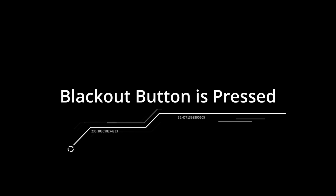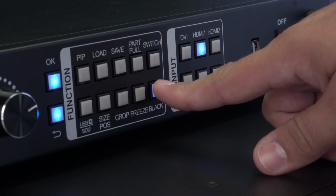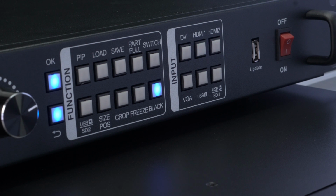The blackout button is pressed. Verify that the blackout button on the front panel of the processor is not pressed. This can block the signal path of your video source.